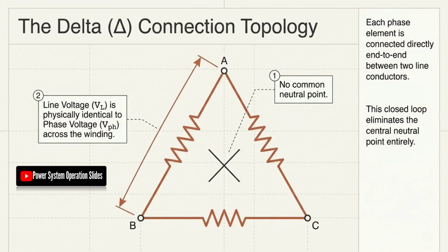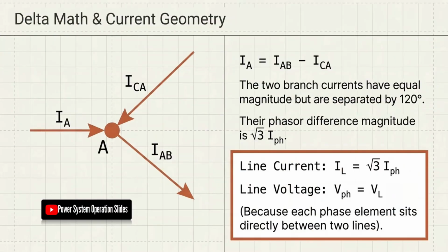Delta-connected transformer windings are therefore commonly used in applications involving variable frequency drives, rectifiers, arc furnaces, and other nonlinear loads. Although a delta winding provides useful harmonic containment, it should still be supported by appropriate harmonic studies and additional filtering when harmonic distortion is significant.